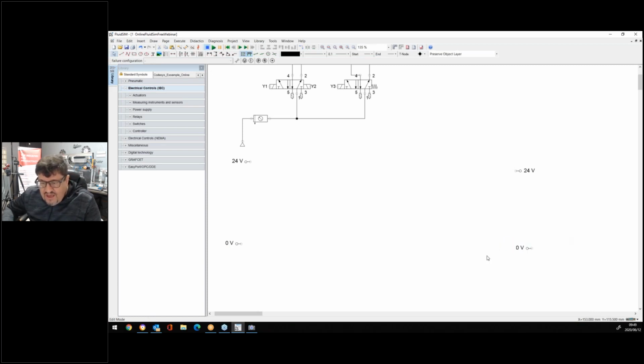Right, like Charles explained to you, you can flip, turn or rotate any component that you put into your circuit. I'm going to click onto the 0 volt, go to that icon on top for rotating. I assume everybody can see the rotation, 90 degrees. Click onto it once again. Then I'm going to connect the two lines. I connect my 0 line to the 0 line here. I moved everything into position so that it looks nice. The same with this: I click onto the 24 volt and connect to that side. Right, there I've got my two power lines now.